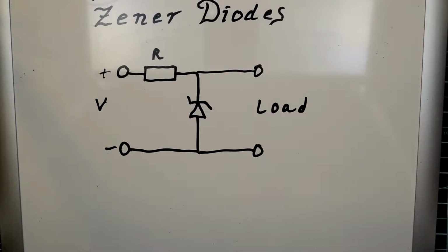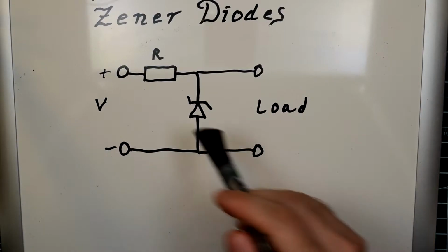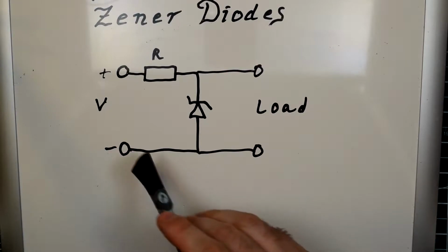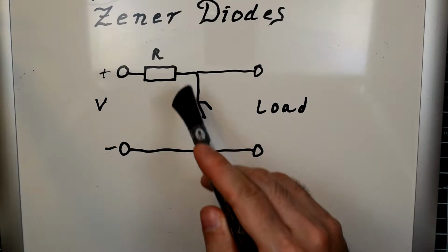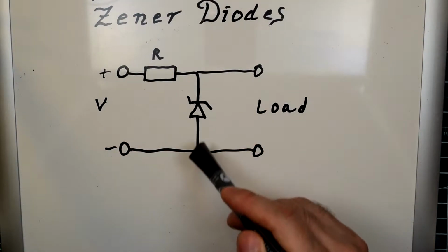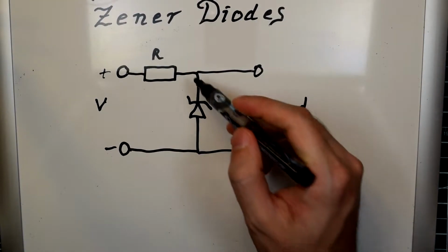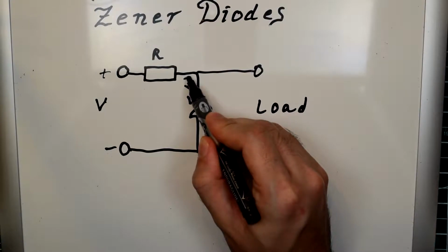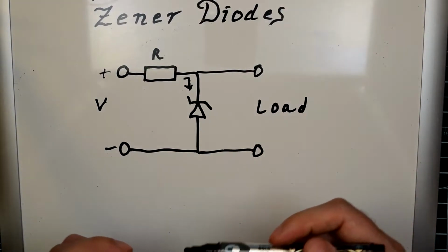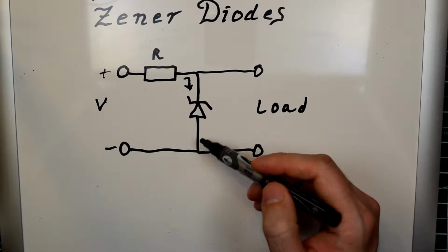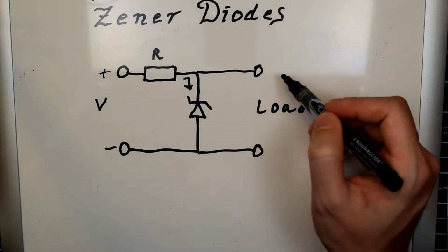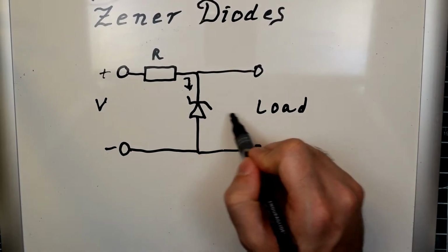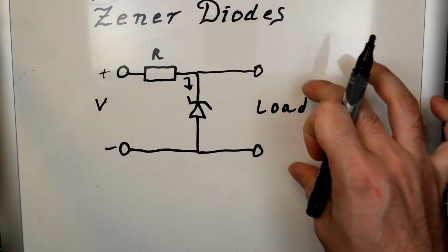So basically what happens here is you're going to have the voltage, and as the voltage rises, when it reaches the voltage of the Zener diode, it will start conducting in this direction. And being as a Zener operating in its reverse biased condition has a very low impedance, the voltage here will be equal to the voltage of the Zener diode, because it's of course in parallel.